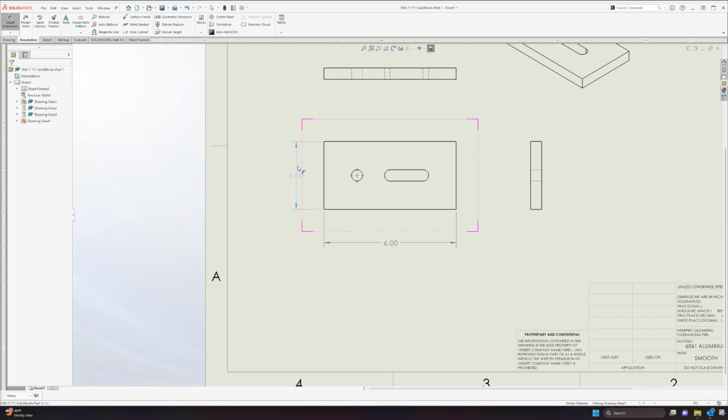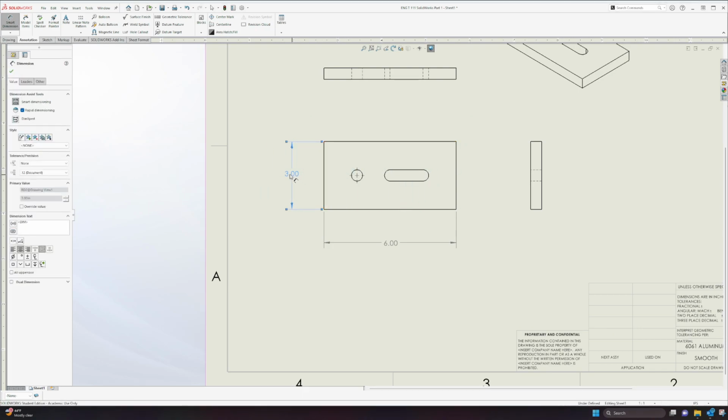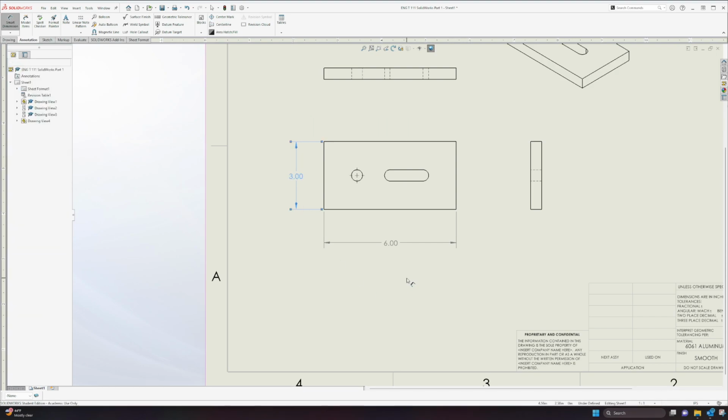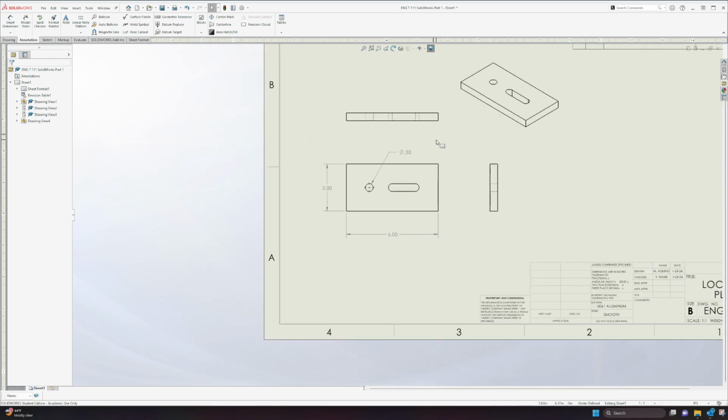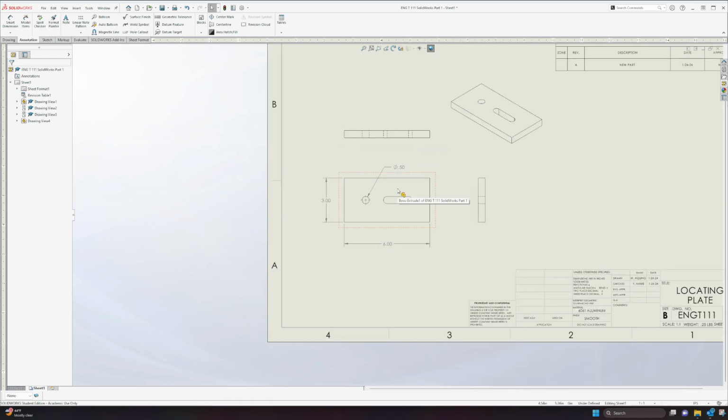And since this 3-inch dimension here is a vertical dimension, you can move it left or right relative to the edges of the part. And same with a circle. If you select it, then the dimension comes out, and with a slot. So what I'm going to show you is actually a quicker, faster way to dimension, rather than having to pull out every single dimension on the part.